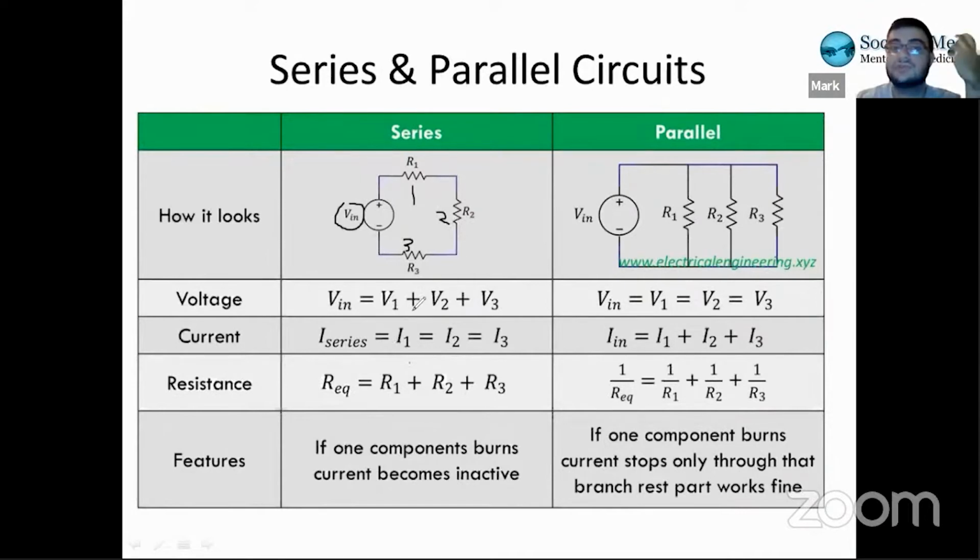So to find the total resistance of the circuit, right? Each of these resistors has its own resistance. So for example, this one might be 2 ohms, and we'll cover the units a bit, 3 ohms and 5 ohms, right? But the total resistance of the circuit is the addition of all of them, the sum of all of them, which in this case is 10.